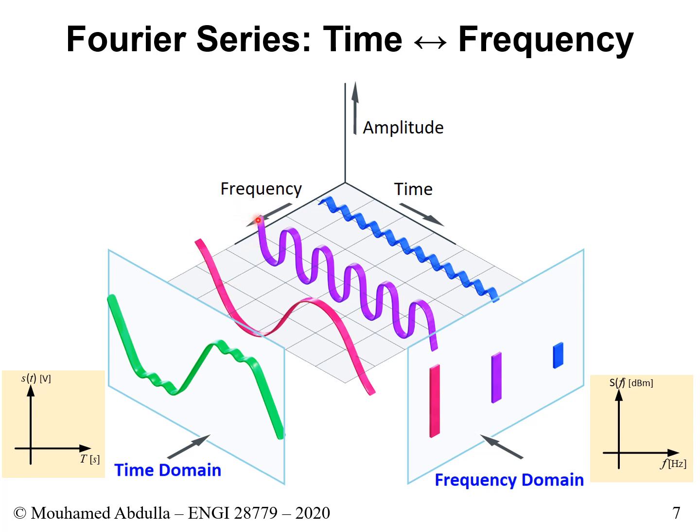F naught is the fundamental frequency, the first frequency. With his equations, with his mathematical tool, he tells us how much voltage we have at each of these different frequencies. And that's where the whole idea of an infinite series comes into place. So, for instance, in this picture, based on this equation, you have a big contribution of voltage at this one here, the third harmonic.